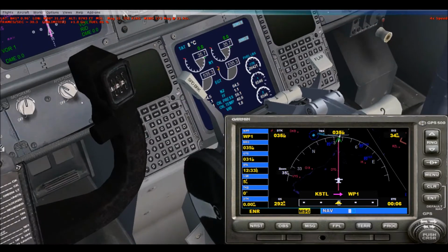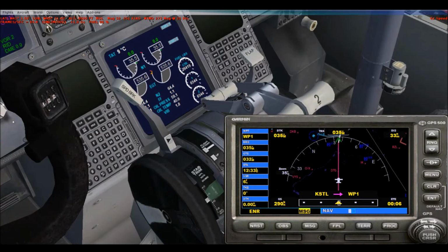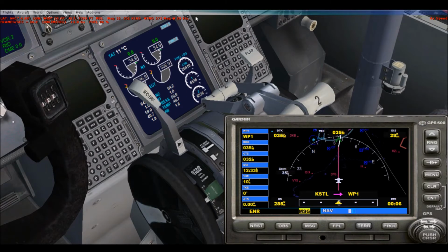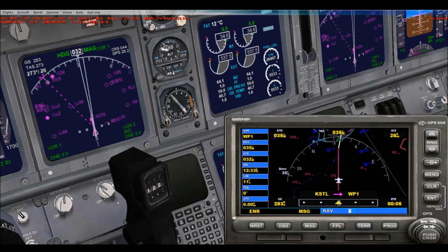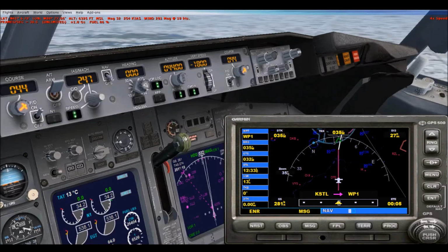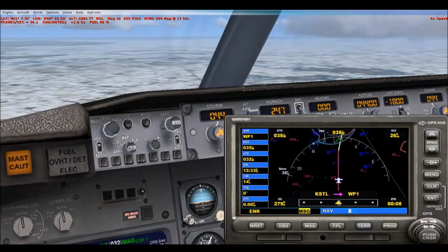In preparation for landing, we can already arm the speed brake by pressing Shift and slash next to the Shift at the same time. And that speed brake you saw move, it's now in the armed position, which means as soon as the wheels touch the ground, the spoilers will engage, and that'll make us stick to the ground, which is what we want.